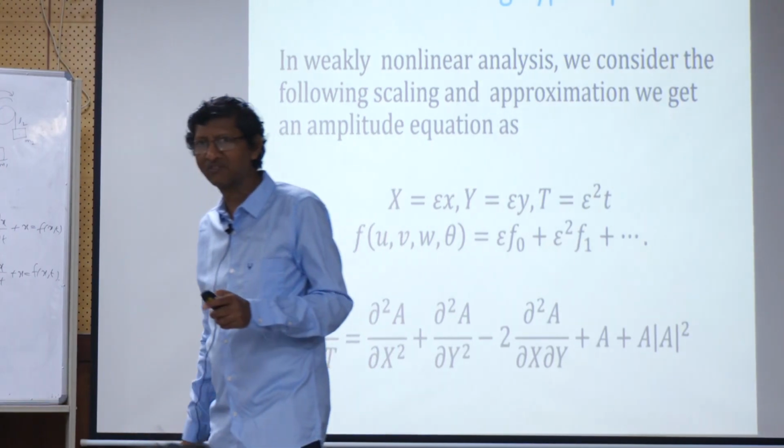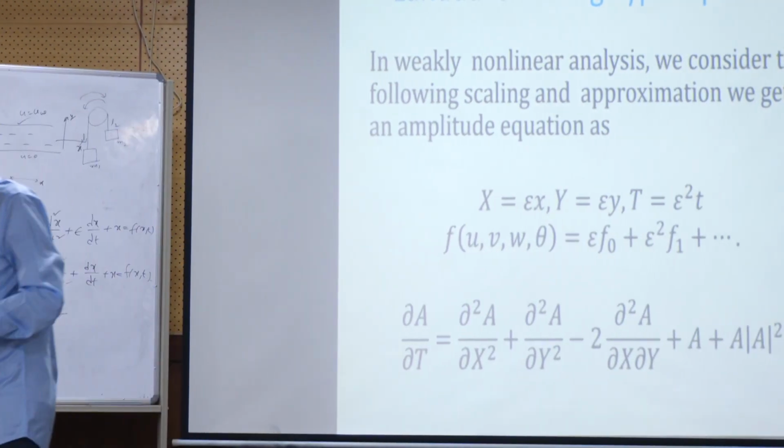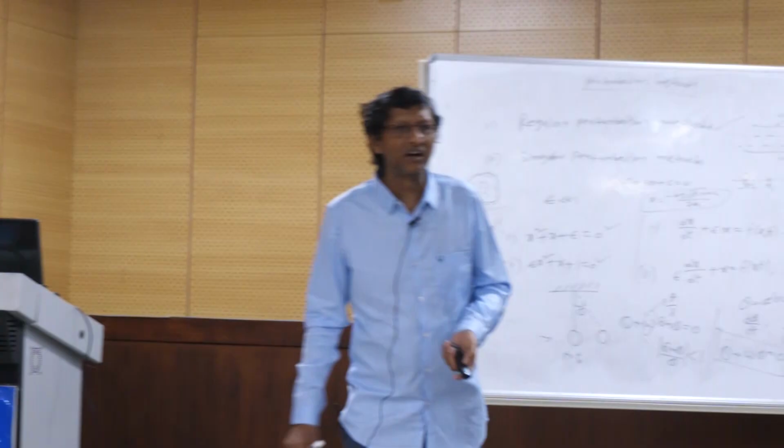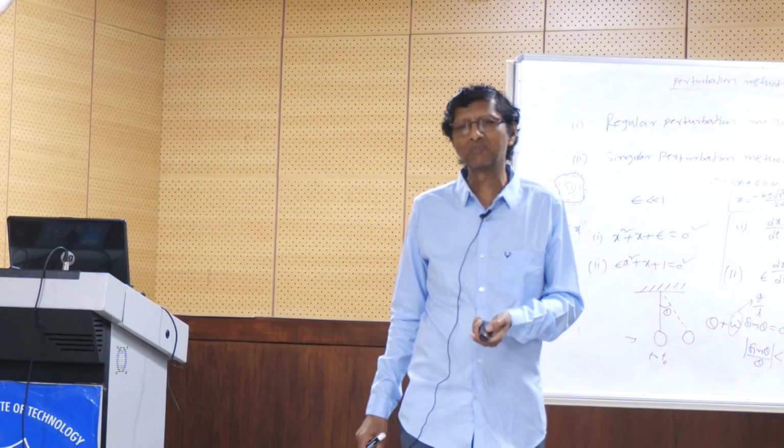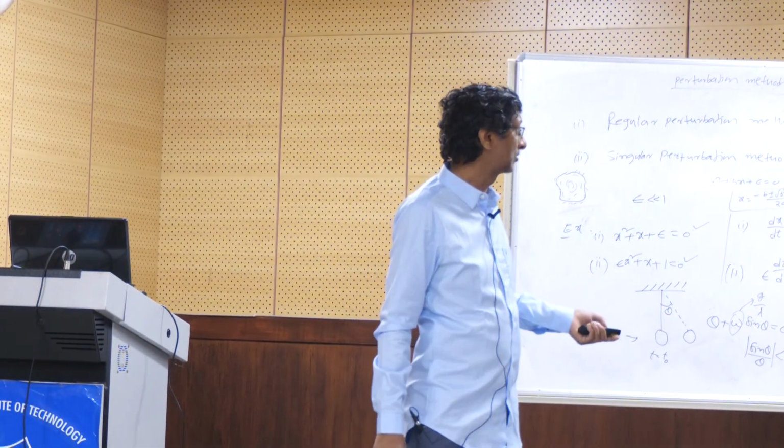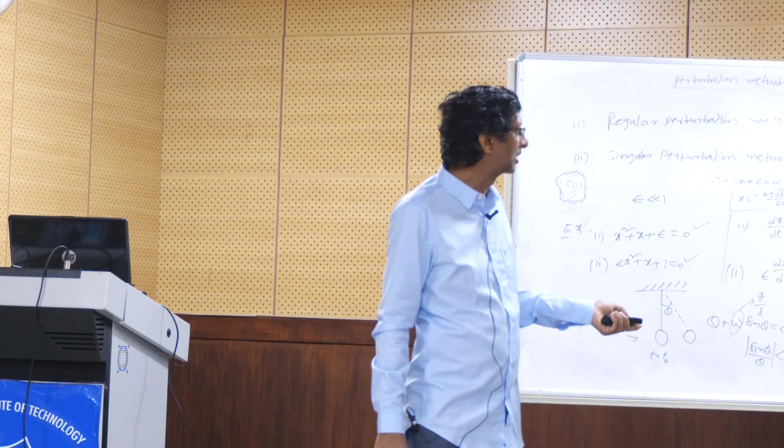Because initial stage means what? As I told you, we get the conduction state, later convection. But at the convection state, what type of flow behavior will there be? Whether it is kinetic behavior or weak turbulence, etc. Those things one can trace out with the help of this equation. It is called the asymptotic equation.